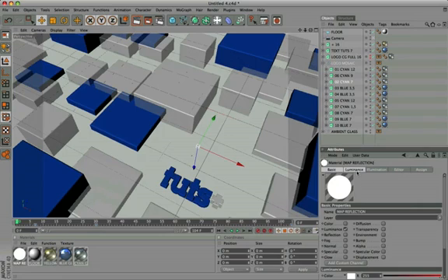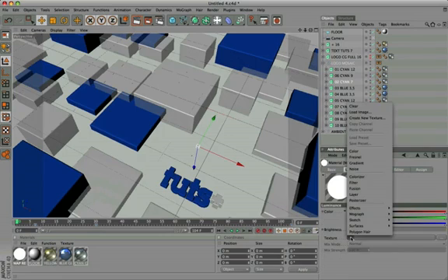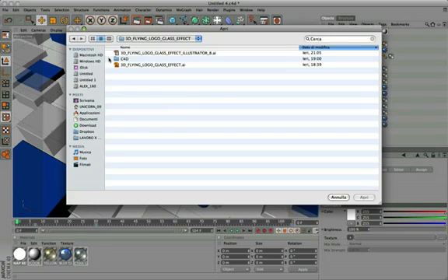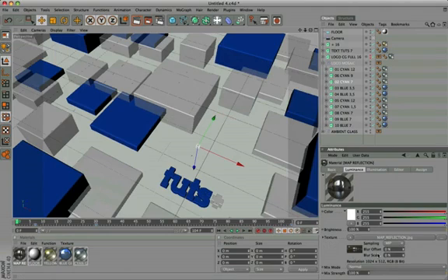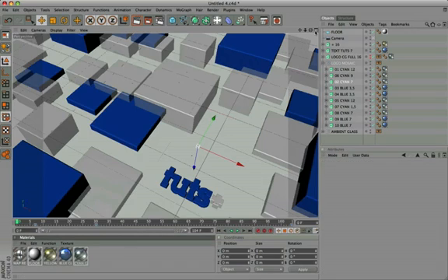Let's go to the luminance panel and load the image, map reflection JPG. We set the brightness from 100 to 500, mix mode to multiply, and mix strength to 35. OK, this material will be applied on a reflective sphere.